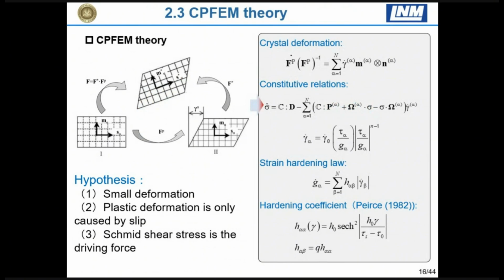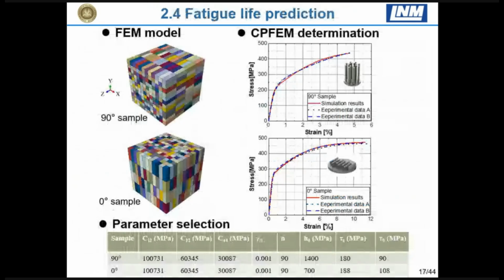So we want to conquer, for instance, one of them. We need to consider the microstructure here. We already know that crystal plasticity can consider dislocation movement and damage, plastic accumulation, and deformation. Plastic deformation is caused by slip, and this framework is well established. With this method, of course, we can do some analysis. For instance, we can get the RVE, the representative volume element. And with this RVE method, there are also many parameters in the various steps.